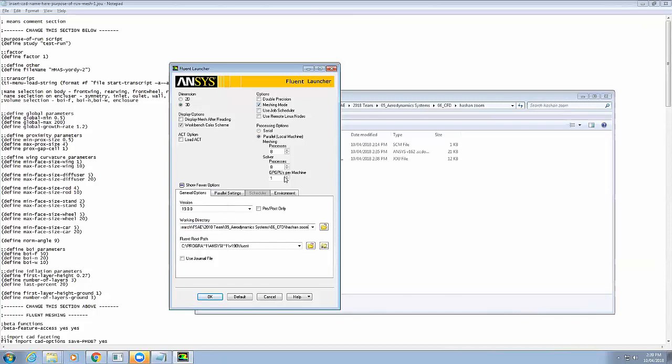Okay. Meshing, that's fine. I wouldn't just leave GPUs out of it for now. So in CFD, all that matters is physical cores, not virtual cores. Where do I check that from? Sorry? No, because I've been doing this, I kind of know. Normally when it says 12 cores, it means 6 virtual, 6 physical.